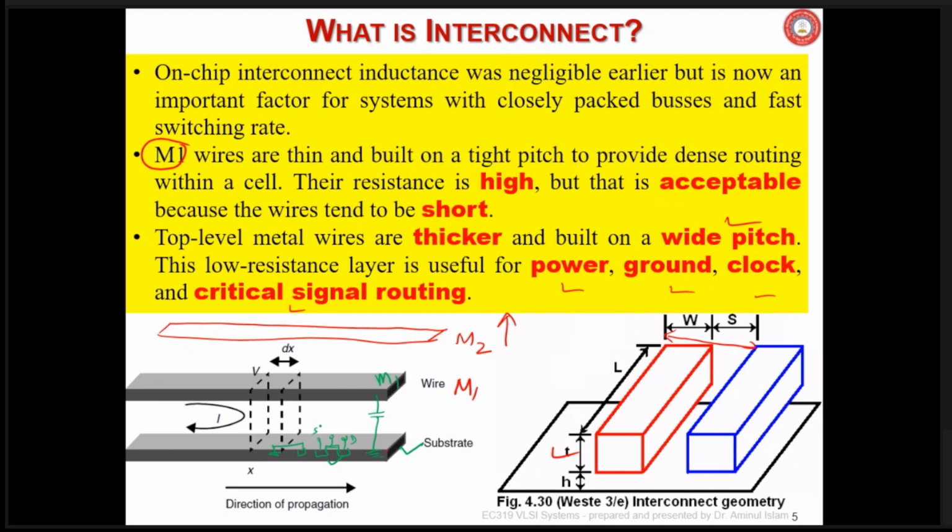On top of that you will have silicon dioxide to isolate. You have the metal one layer, and above that again a SiO2 layer, and then another metal layer. In this way metal layers go up, maybe up to 10 metal layers are available nowadays in new processes.